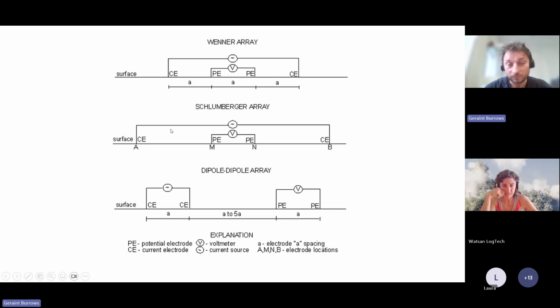But if there were no boreholes around, you would do a vertical electrical sounding to start to understand what depth you get to when you encounter the harder rock. The sounding will give you an approximation of the depth of the crystalline rock at that particular point. And then you would use that to decide on your distance separations to then do the traverse.